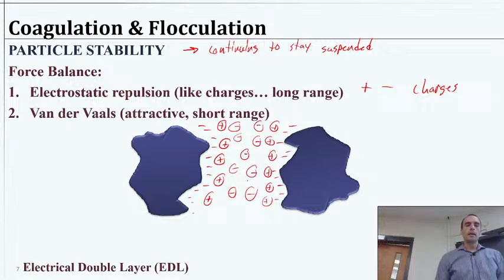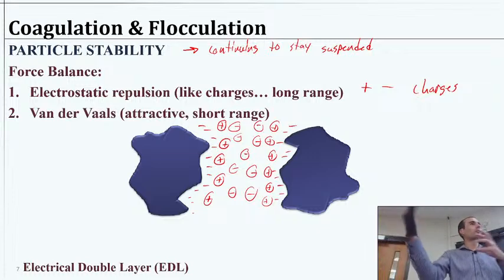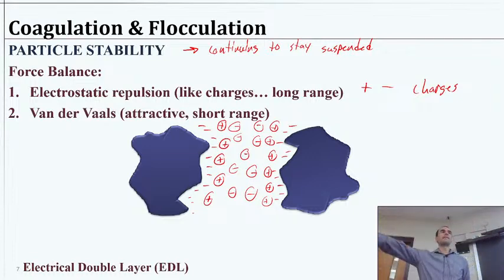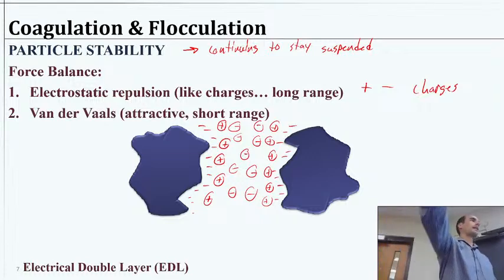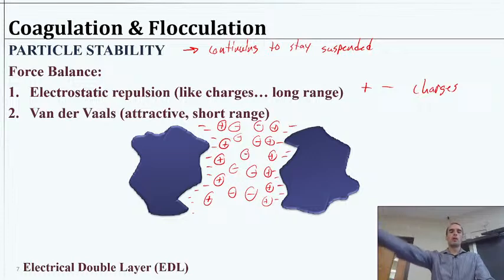So in this way, and there's going to be some positive charges floating around because these are diffusing a bit, but you'll have this net double layer that really extends out that repulsion, because now you have not just the charge at the surface, you have a charge that has been communicated out into solution based on these ions. So that's part of the long range. What we want to destabilize the particles is to really shrink that, to remove that effect, so that the particles can get close enough to stick. Okay? So then, these van der Waals forces, you can think of the gecko. Is there a C there? I don't remember. We'll say there is.